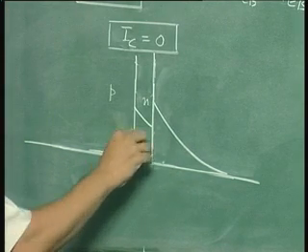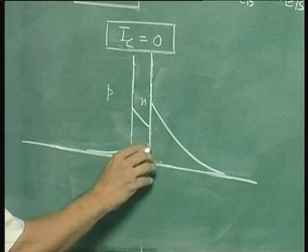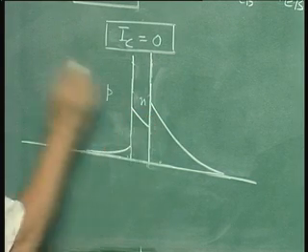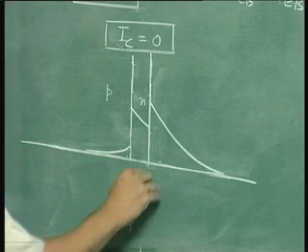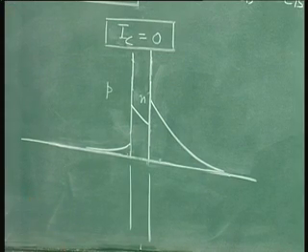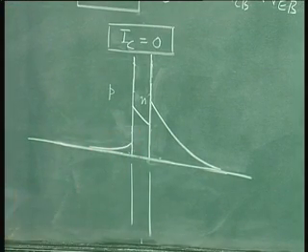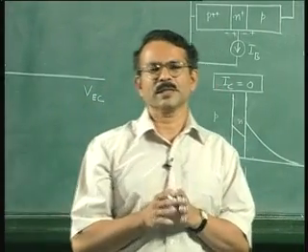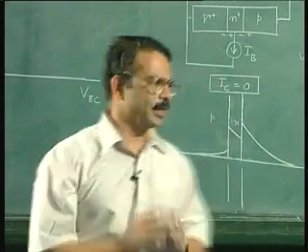So now we need to find out for what kind of voltage condition the current on the collector will become 0, and how can the current become 0? So let us draw the flow diagram again as we had done earlier. Now when we draw the flow diagram, we will continue to ignore the recombination in the base, because we are assuming a modern transistor. We have said that in a modern transistor the recombination in the base is negligible, and that helps us to simplify the picture greatly.